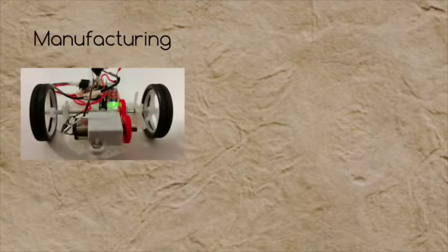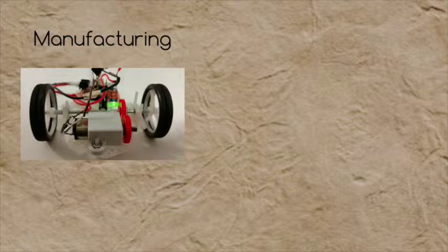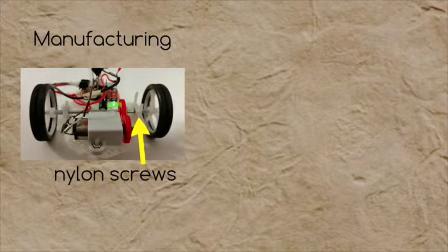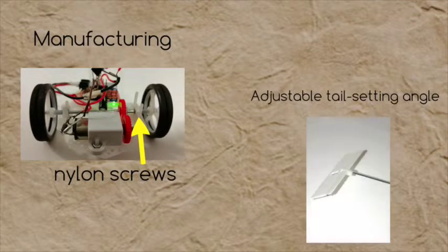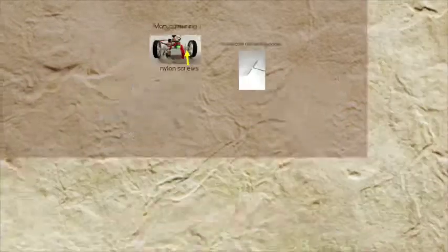The manufacturing process exposed certain weak spots in different components. Indeed, the way the bearing housings were attached to the base plate proved to be insufficient in accuracy to perfectly align the drive shaft. A new design included screws to remove the dependence on an adhesive. On the other hand, having an adjustable setting angle for the horizontal tail proved to be very beneficial.